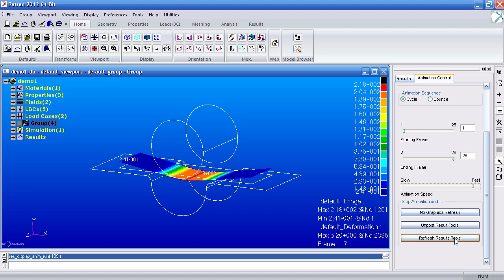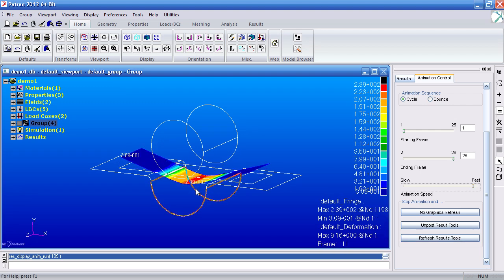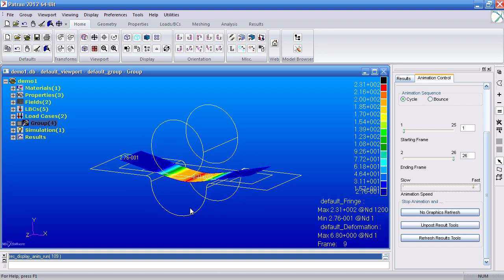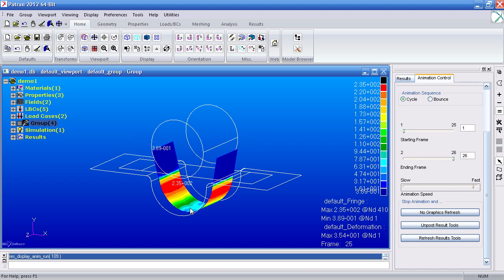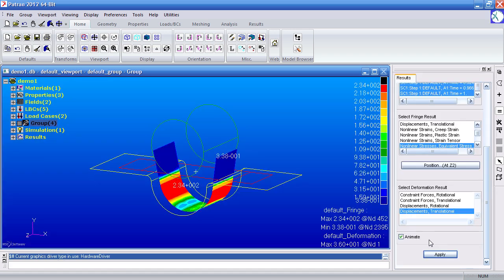At this time, you can query the stresses and strain and see if Nastran is following the stress strain curve that you defined through the CSV file, by outputting the stresses and strains, and you can backtrack and overlay it on the CSV file's stress strain curve and see if Nastran is following it exactly the way you defined. Okay. At this time, that concludes my demo. I'll go back into my presentation.